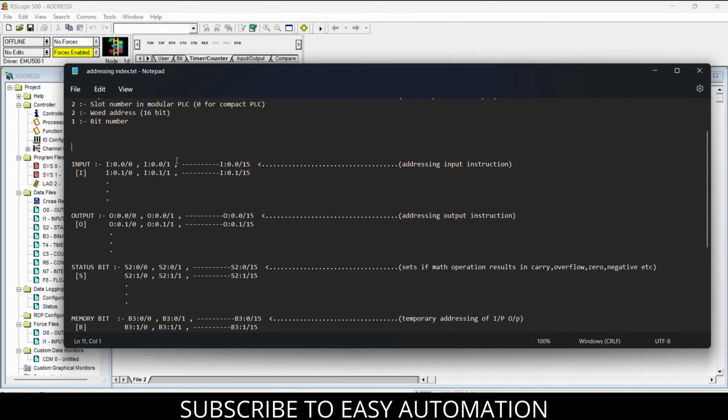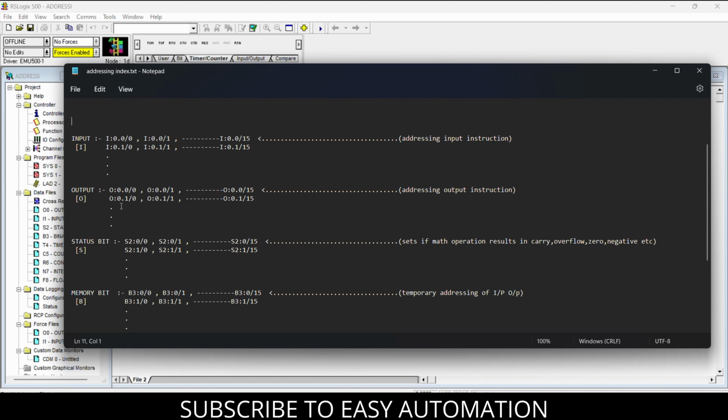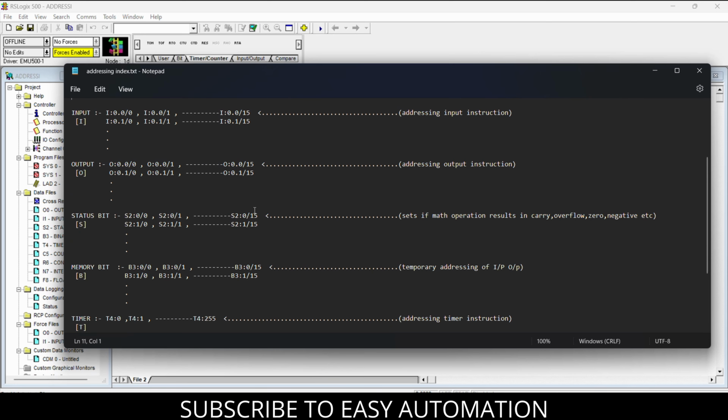If I want to summarize this session, I will summarize like this. We can use our input address for addressing our input instructions, which goes like I:0.0/0. You can use the 16 bits from word address 0, word address 1, or whichever word address you have. For output, we can use the output addressing from O:0.0/0 to O:0.0/15. So this is also 16-bit addressing.